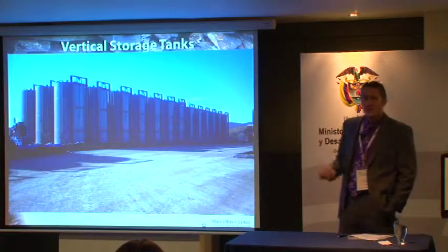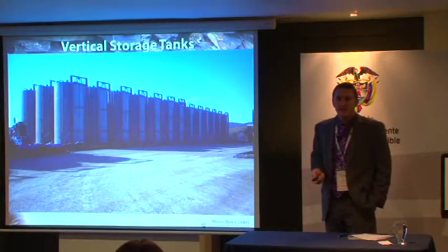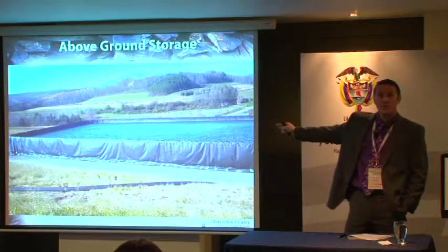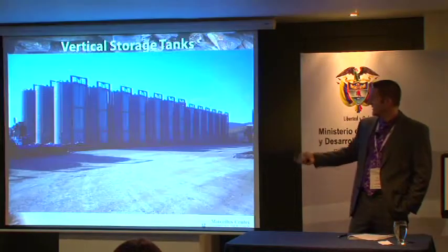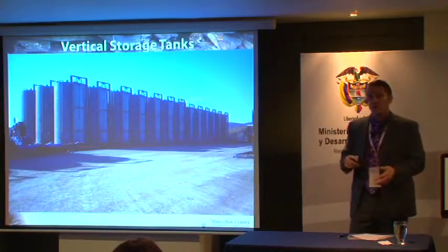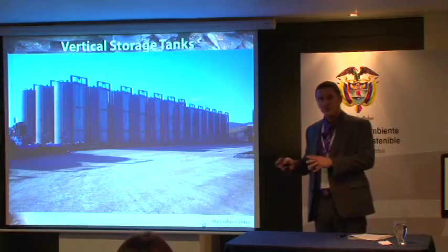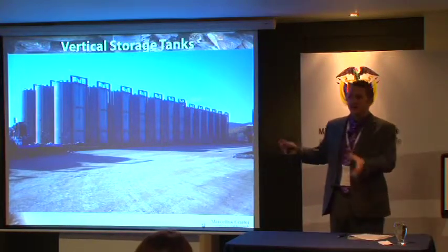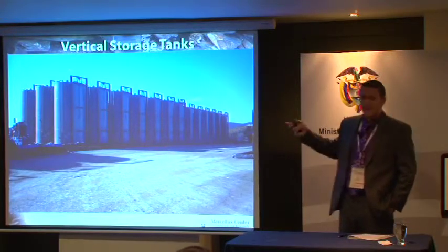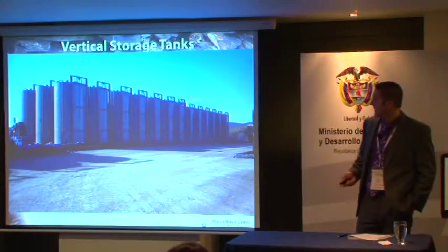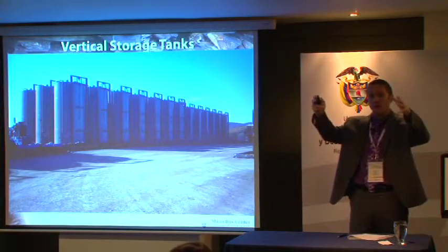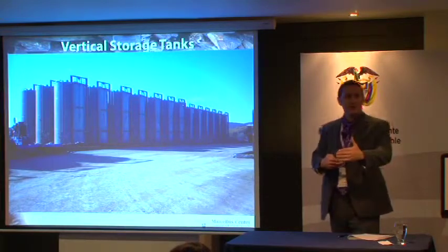We're also seeing more vertical storage tanks being utilized out there in the field. I should note that this is only allowed for fresh water, whereas with a vertical tank like this, you could use it for both fresh water or the produced water. So a little more versatile. Again, these can be brought into the site and taken off and used at another site once completed, again minimizing that surface footprint. And the nice thing is because they're vertical, you can store more water over a smaller surface area.